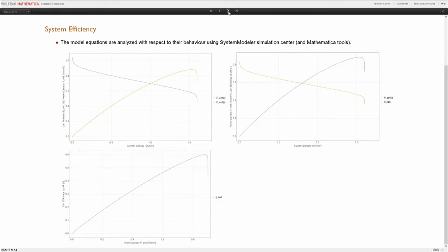And this shows the motivation why fuel cells are considered to be quite efficient for low load, because for very low current density they show a very high direct electrochemical conversion efficiency, up to the theoretical value of up to 83%.